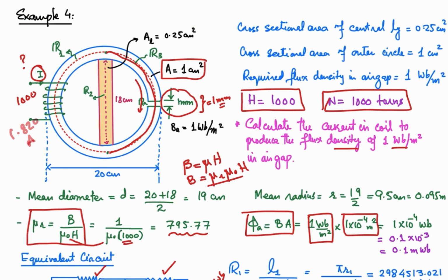Current is analogous to flux, or flux is analogous to current. MMF is just like the voltage source, reluctance is just like the resistance. Develop the electrical circuit, apply electrical laws, and solve it, analyze it for any required parameter. So magnetic circuit can easily be solved by the information of the electrical circuits.